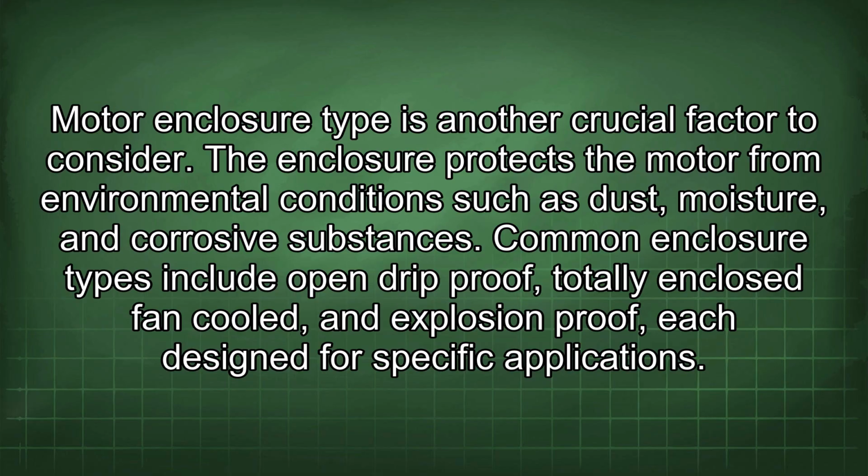Motor enclosure type is another crucial factor to consider. The enclosure protects the motor from environmental conditions such as dust, moisture, and corrosive substances. Common enclosure types include open drip-proof, totally enclosed fan-cooled, and explosion-proof, each designed for specific applications.